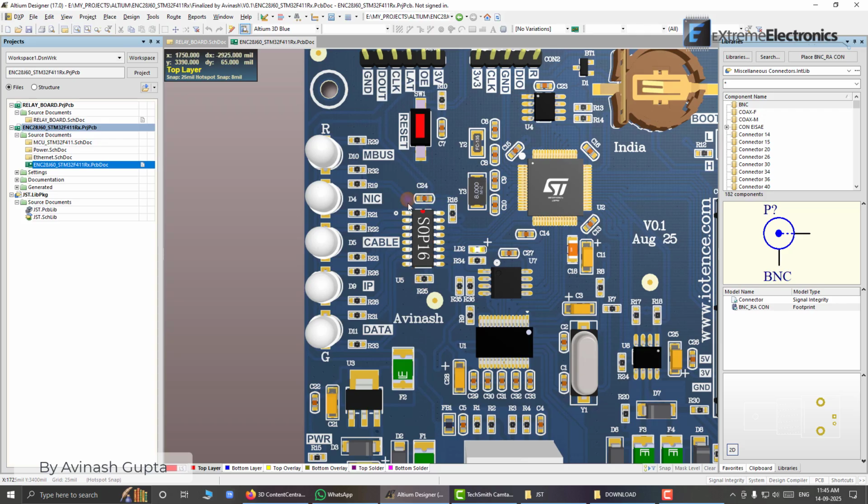So this shift register is controlled by these signals: we have data, we have clock, we have latch, and we have OE or output enable. All these lines control this shift register. It is the same parallel connection and the cascaded data out connection. The clock, the latch, the OE are all parallel with this shift register, but this data out is in a cascaded form. So we can easily cascade more shift registers to the same signal without wasting the GPIO pins of the microcontroller.